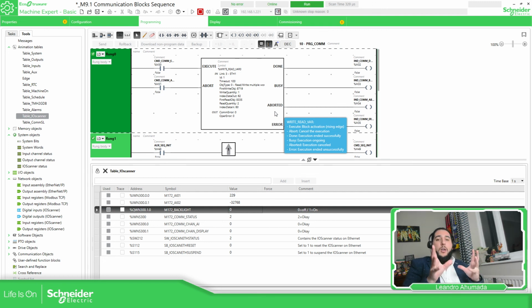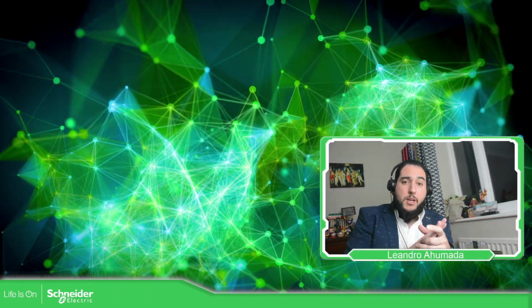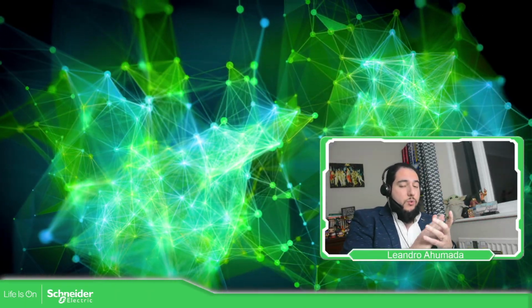You can simplify that by using the IO scanner to just define the table, the channels, and the variables you want in one place, and that's it. If you need to communicate with a device, I recommend you go with the IO scanner rather than the function block. So this is the Modbus TCP IO scanner for the Modicon M221.